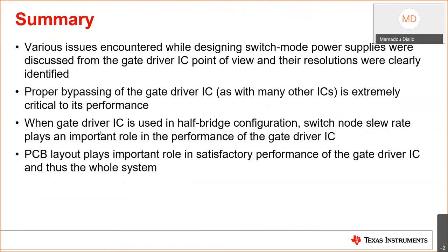So in summary, various issues are encountered in the gate drive portion. This is commonly related to either biasing supplies on the VDD pin or VCC, or also on the HB-HS capacitor or the bootstrap network. Sizing these is critical to ensure that you're getting the best performance from your gate driver IC.